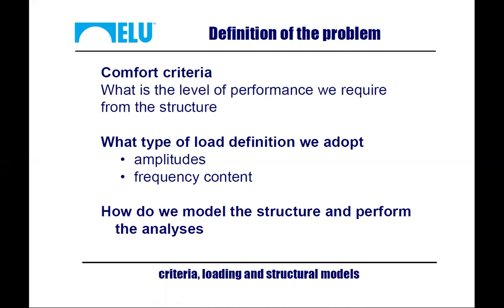And since we are talking about dynamic problems, we will need to look not only at the amplitudes of the load, so at the maximum force that we apply, but we also need to look at the frequency content of the loading. So what type of frequencies are present in our load definition. Then, of course, that will come a bit later. We need to do a modeling of the structure and perform the analysis. I'm going to talk about this on a practical example.